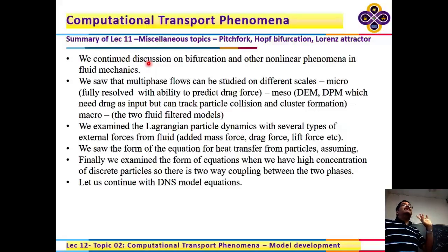In COMSOL, I'm arguing that COMSOL should give you the correct pressure field. Why am I arguing that? Because COMSOL has to satisfy both the momentum equations. There is the other momentum equation, which is the R momentum equation. In the Z momentum equation, every term would be 0.